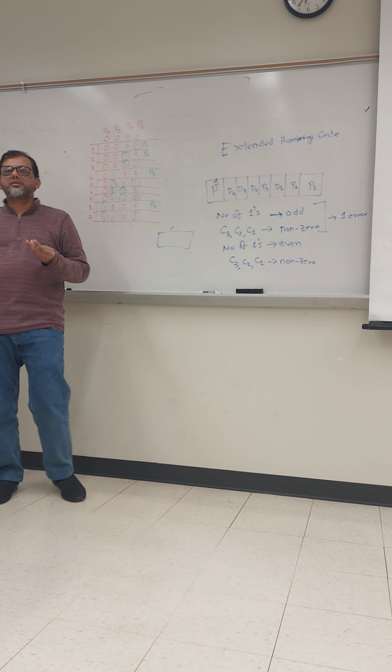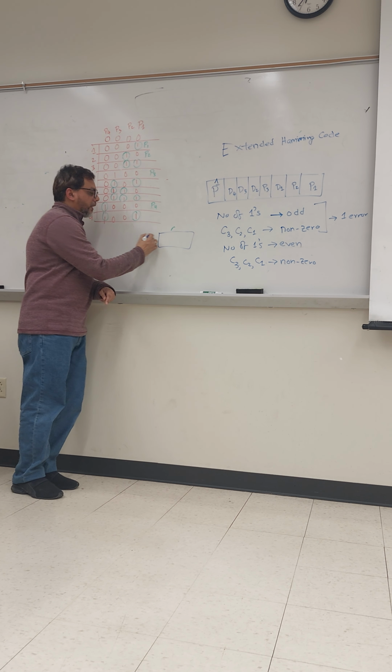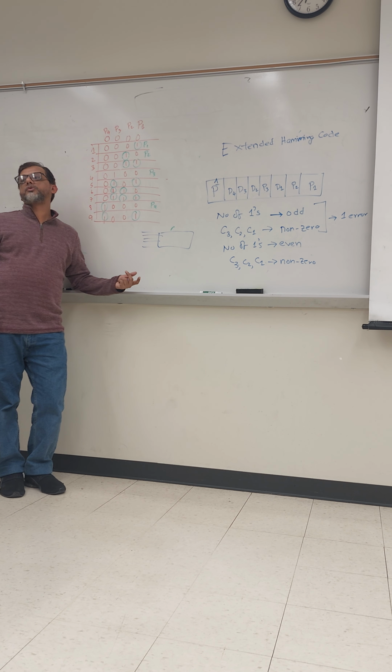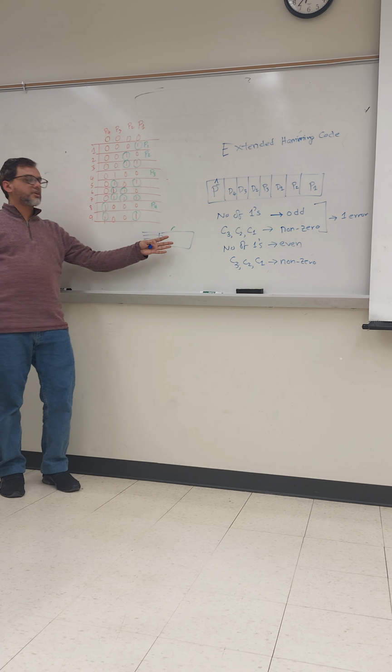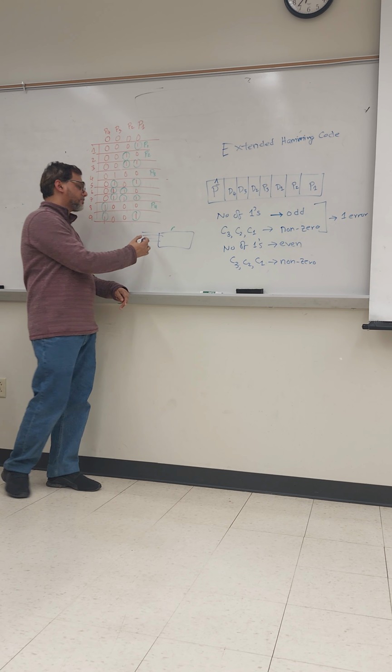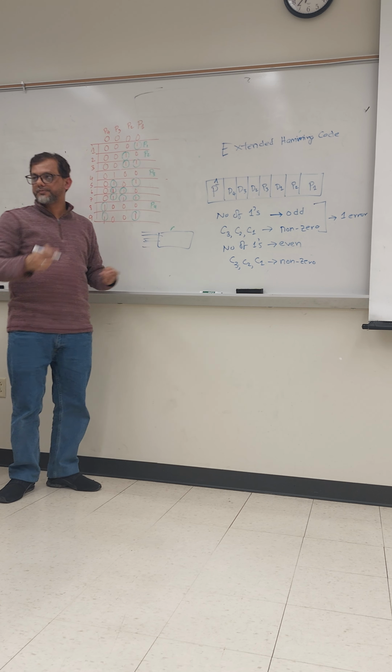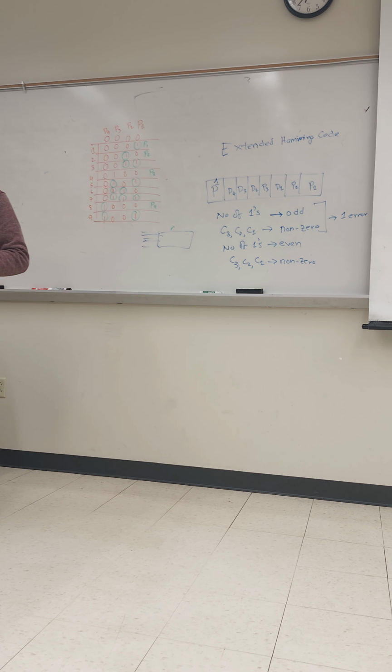So you can make a 5-input NAND gate, but we usually do not do that, otherwise it will increase your complexity. Rather, we should put a 3-input NAND gate, take out the output, then give it to another gate. So it's possible. But the output of the AND gate will be high when all the inputs are high.